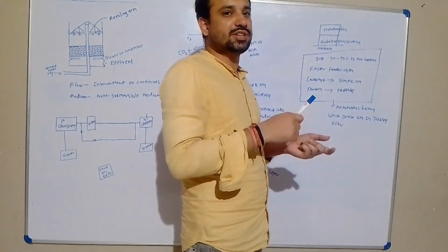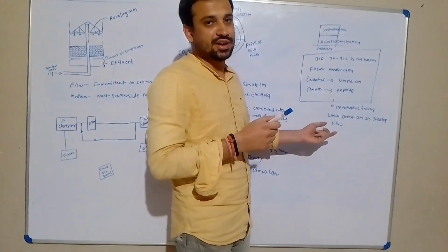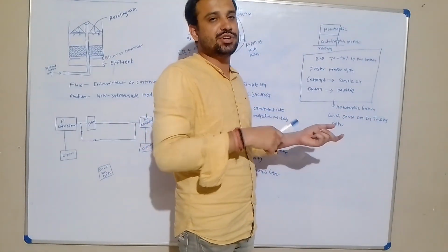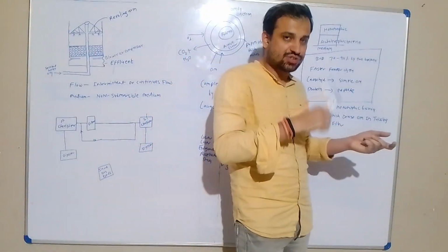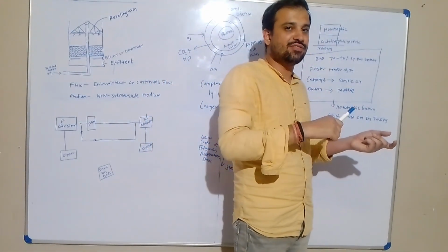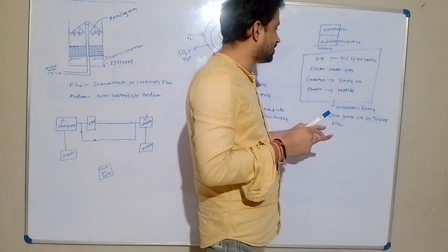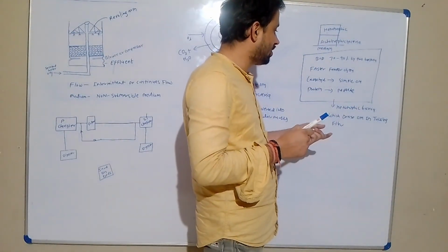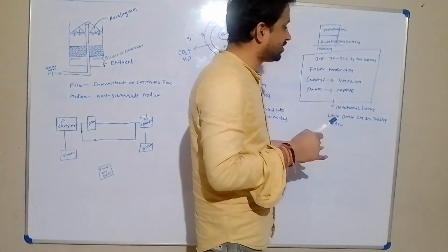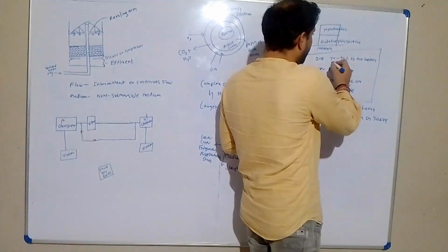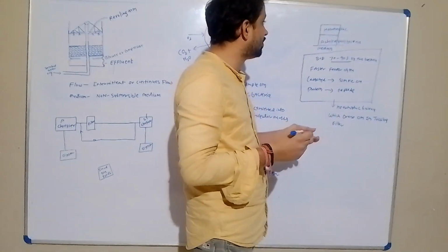Satisfying the biological oxygen demand means the organic matter decreases in the trickling filter and O2 is reduced in the wastewater. Organic matter decreases in the wastewater after the filtration process. And the biological oxygen demand is satisfied by 70 to 90% by these heterotrophic bacteria alone.